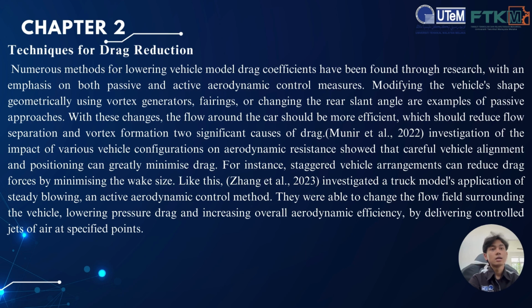Likewise, Zhang 2023 investigated a truck model with application of steady blowing, an active aerodynamic control method. They were able to change the flow field surrounding the vehicle, lowering pressure drag and increasing overall aerodynamic efficiency by delivering control jets of air at specific points.